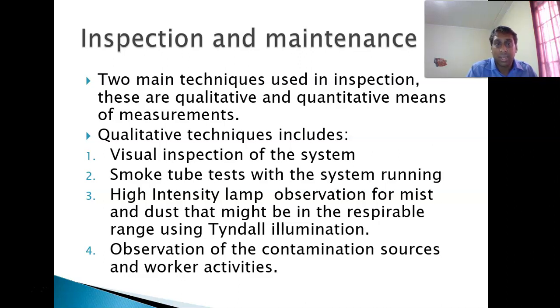So the smoke tube, if you know what this one is, a lot of people in the old days would normally have used a cigarette for this, but a smoke tube is something that you can buy. You simply break the end of it, sort of like a test tube, and a plume of smoke comes out of it. Because it's like a vacuum system, you can look and see if the smoke is being sucked into the hood.